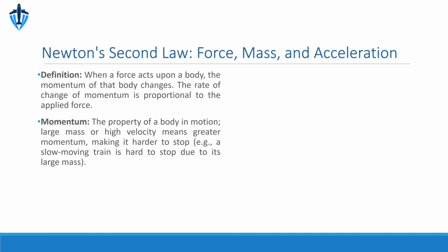As we've seen, when a larger gear drives a smaller one, the smaller gear spins faster but with reduced force. For a system to be a force-gaining machine, the smaller gear must do the driving of the larger gear. In aviation, terms like propeller reduction gearbox indicate that the engine's input RPM is higher than the propeller's output RPM. This reduction in speed is precisely what allows for an increase in torque at the propeller, optimizing its performance.